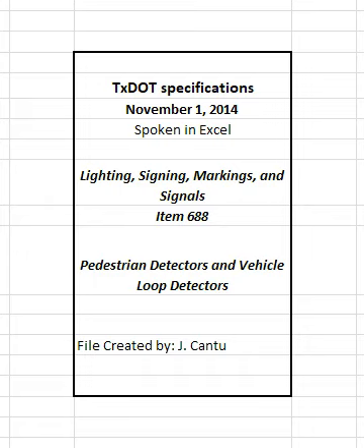Ensure the push-button assembly is weather-tight and tamper-proof, is designed to prevent an electrical shock under any weather condition, and has provisions for grounding in accordance with the NEC. 2.1.1 Standard pedestrian detectors. Provide a two-piece cast aluminum housing unit consisting of a base housing and a removable cover. Provide threaded holes for 0.5 in conduit in the housing for any necessary conduit attachment. Ensure the manufacturer's name or trademark is located on the housing.